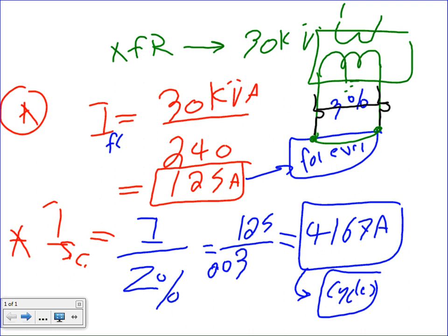The circuit breaker should be rated to handle this amount of current and trip within cycles. We talked about last night 3 cycles; most of them are within 3 cycles. The circuit breaker should be designed cover-wise and insulation-wise to handle this huge amount of current for a very short amount of time, guys. All these are rated for 3 cycles. 1, 2, 3 cycles, bam, the circuit breaker will open. It is rated to handle this amount of pressure for 3 cycles, no problem. Nothing is going to burn. And the circuit breaker is rated to interrupt this amount of current.